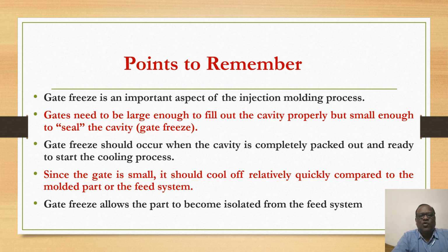The gate freeze should occur when the cavity is completely packed out and ready to start the cooling process, because after that you have to give time for cooling, and then only the component will be ejected. Since the gate is small, it should cool off relatively quickly compared to the molded part or the feed system. Gate freeze allows the part to become isolated from the feed system.